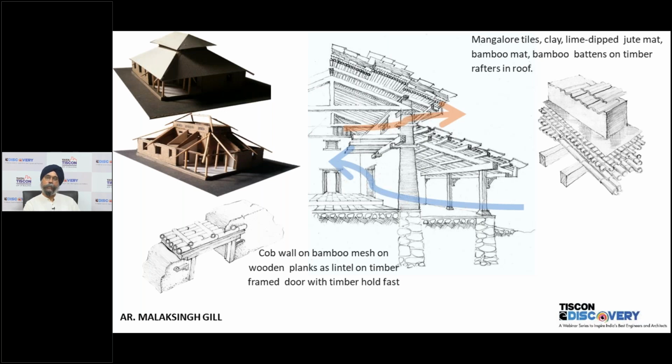And you can see the right corner where all the layers of materials which are there above that roof are. This is to reduce the temperature intake of the building, but also to prevent the roof tiles from cracking when the monkeys who come into this area because there is farmland will jump on the roofs. So details have been developed keeping in mind a lot of real problems which people face.